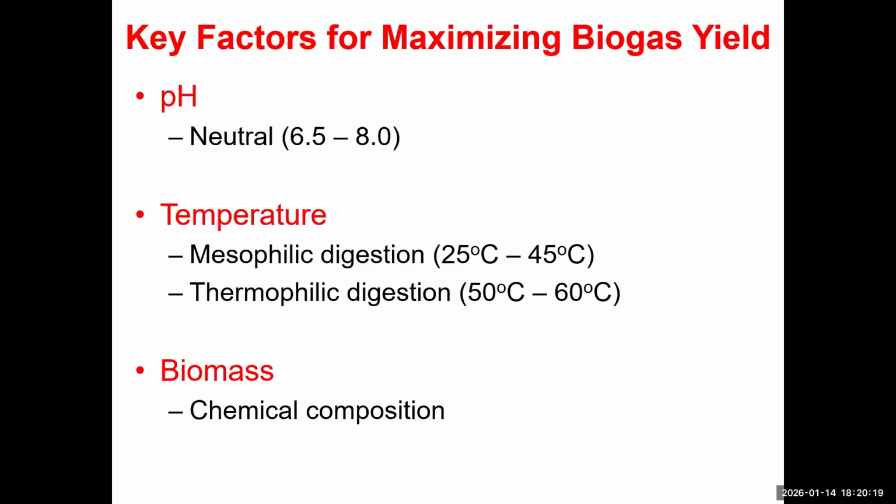That means that those reactions are occurring faster, so the faster methane is being produced. Although you do get faster methane production in these thermophilic digesters, research has shown that these thermophilic bacteria are more sensitive to environmental changes. So these thermophilic systems aren't as stable in comparison to a mesophilic digestion system.